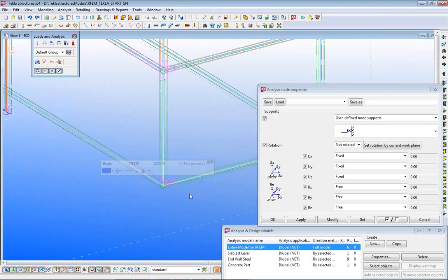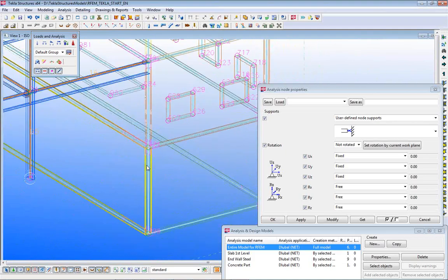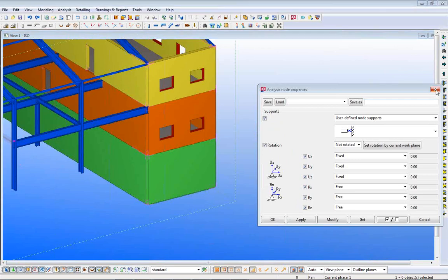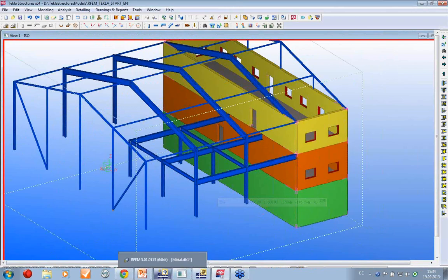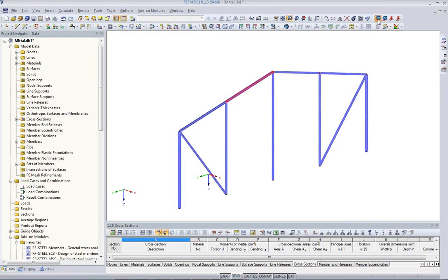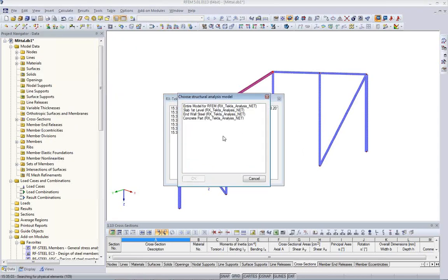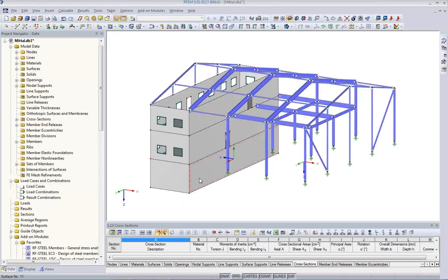Okay, also here the walls are modeled as center lines, and the slabs as well. So I'm closing the model here and staying with the physical model view, and I start inside RFEM and import the analytical model, including rigid links, which I don't have at the moment, and I click OK. Now I choose the entire model, click OK, and we are importing the entire structure.